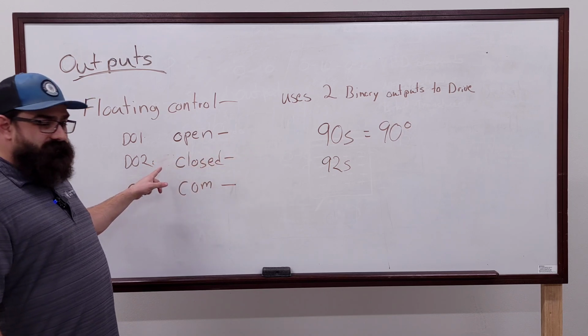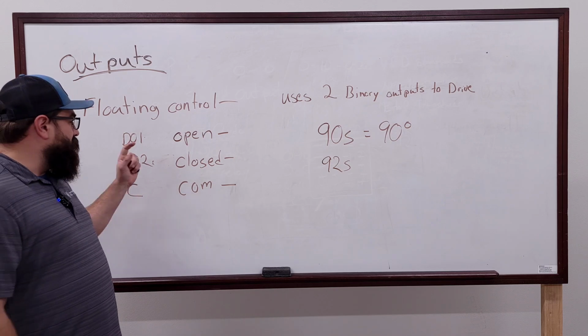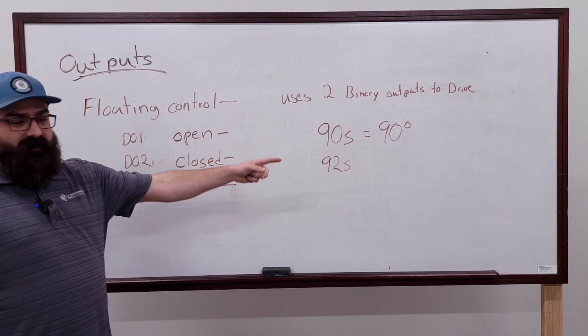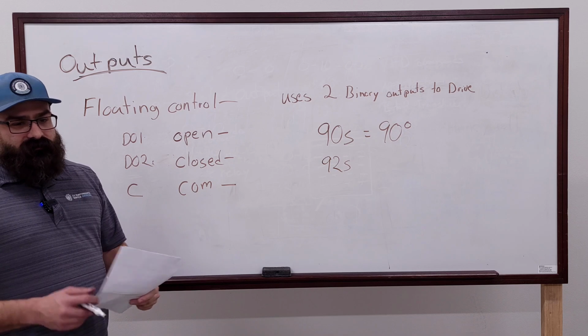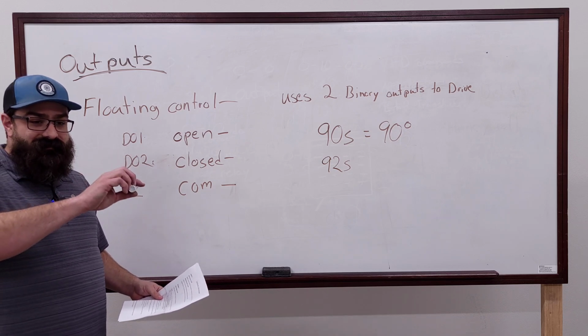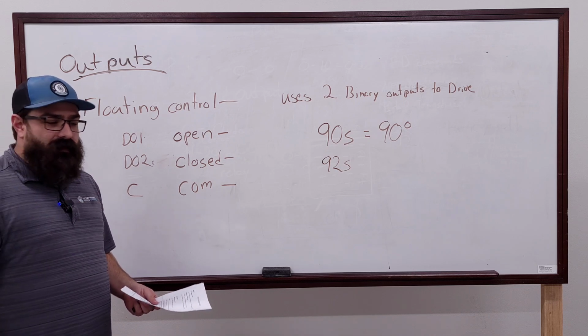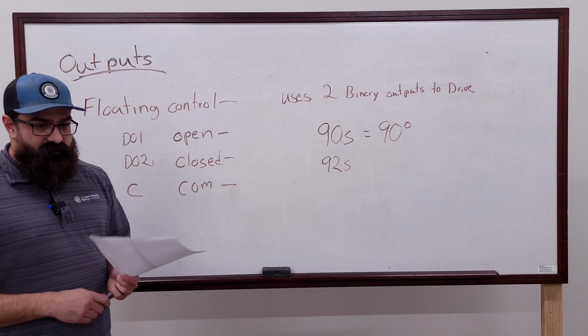Well, when it goes to close it, it's gonna try and overdrive it closed. And then the next time it goes to open, it may go to, let's say, 75 degrees, and then it says, oh, well, I want to close it to 30, and it tries to close it to 30, but it keeps going past 30 because it actually takes longer, and they get out of sync. And that really drives people up the wall because they can't figure out why this actuator is not where it's supposed to be.